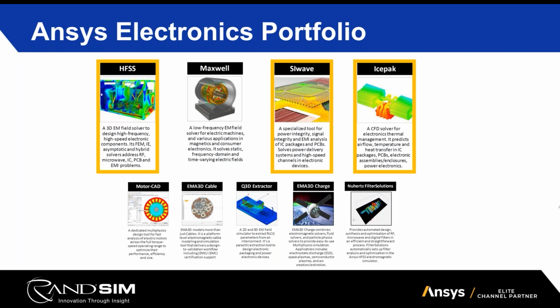It's very wide-ranging. We also have SIwave, which is our specialized PCB tool, which is going to be useful for power integrity and signal integrity within IC packages and PCBs. Lastly, today we'll also talk a little bit about Icepak, which is the electronics thermal solver. This is going to be used for any simulations where you need to look at airflow, temperature, or any heat transfer within any electronics packages.